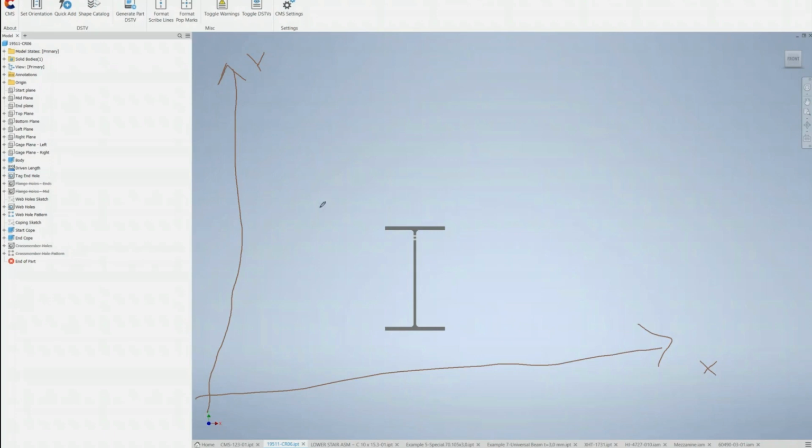We want, on an assembly level, let's say, for example, we are talking about a channel. I want to place that channel as a C on that plane. It could be placed anywhere on that plane, doesn't matter, but it should look like a C. If I have something presented like this one, then I can still work on it, but I have to give an additional manual input through that button over there. So I have to manually set the orientation for that. But again, if you put it like this as a C, then our conversion process would be much faster, right?